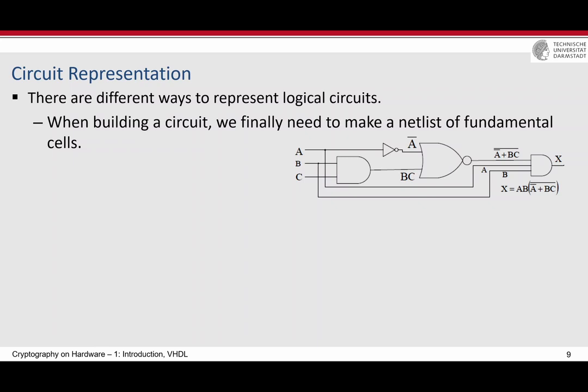In FPGAs, we will see later, instead of these AND and OR gates, these will be implemented by some lookup tables. And then how they are connected together: there are some programmable switches that connect different wires, carrying incoming signals, to different destinations. It can be configured, and this really makes the configurable hardware. It means that the lookup tables you can configure, and the switching matrices you can also configure, and this allows you to build the circuit in any topology that you want.